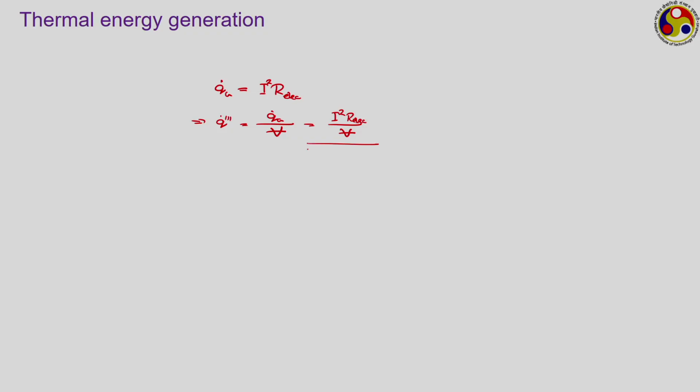But for the moment we are going to deal primarily with this kind of losses, and with a couple of assumptions that are exclusive to this lecture only. We are considering energy generation, but we are assuming this energy generation to be constant. In general, this qg dot triple prime is expected to be a function of time and all three spatial directions. As we have restricted ourselves to a steady state one dimensional scenario, we can write this as a function of x.